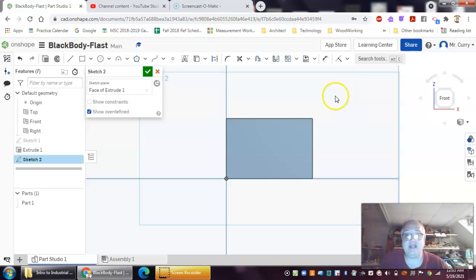And again, we're going to draw a rectangle that matches the shape of that U. As we're looking at that, we know that the cutout part to give us that U measures a half an inch by half inch. Now, I'm just going to come in. Notice I could draw right here on that block, but I need to constrain my sketch a little bit.